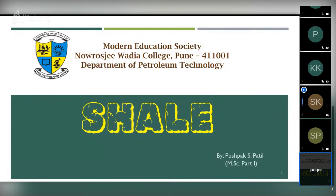So what does the mud system do? It basically gives you the lubricant, the cooling of the bit, and uplifts the cuttings from the well, right? Yes, sir. Now, when we say uplift, from the well it flows through the flow line and comes to the shale shaker. Now, what does the shale shaker do?